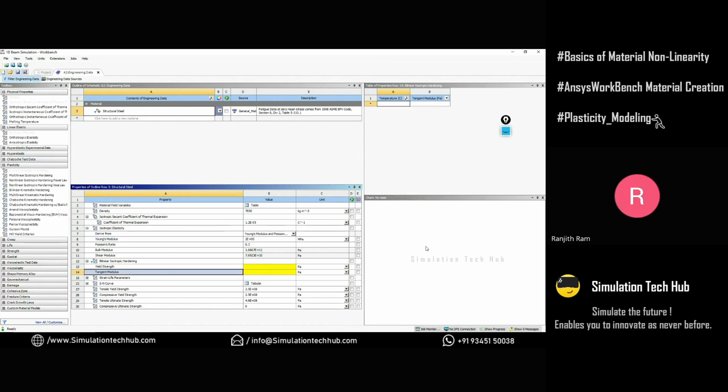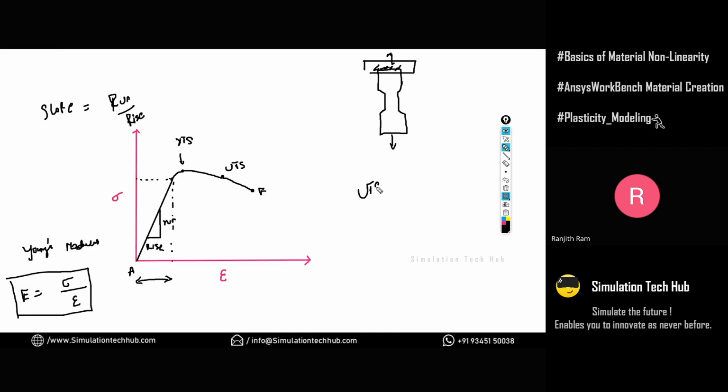It's very easy for me to tell that, okay, hey Subhushri, if you want to calculate the tangent modulus, you will just need three parameters. One is the percentage of elongation of the material, and you need the UTS, and then the yield point of the material. Just go ahead with this formula: UTS value minus YTS, and divide the whole value by the percentage of elongation of the material. That could be the standard formula, but where exactly this formula came from and why we are using it is what matters. Okay, so now we'll understand from this concept.